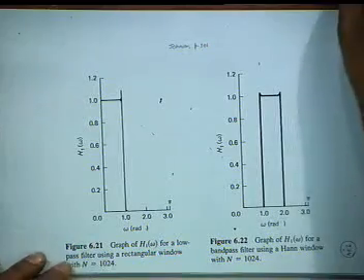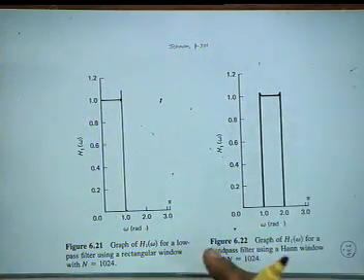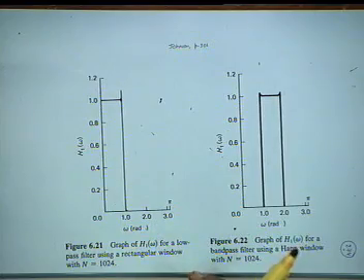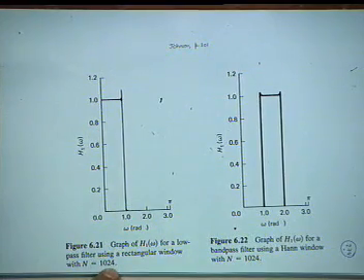Finally, we show a figure where the length has been increased to 1024. It's very large, 4 figure. Actually, I suppose there is a mistake. It's not 1024, it may be 1023, okay, or 1025, because we stick to odd. In FIR design, we stick to odd. Half sample delay is very irritating in many applications.